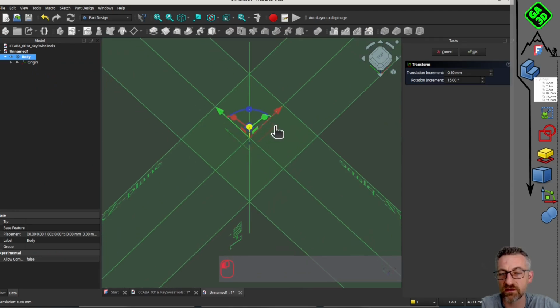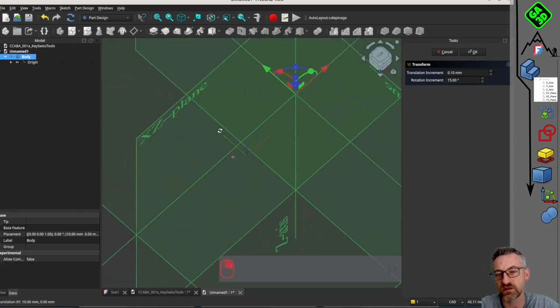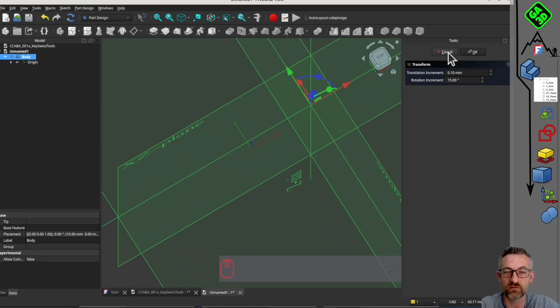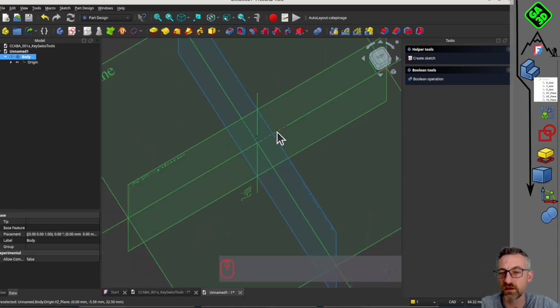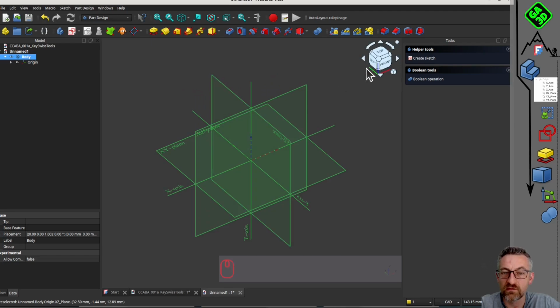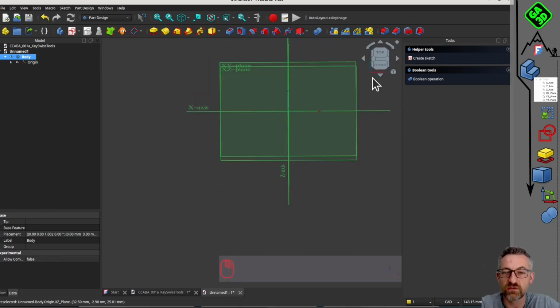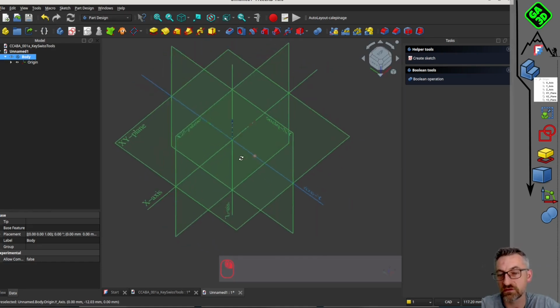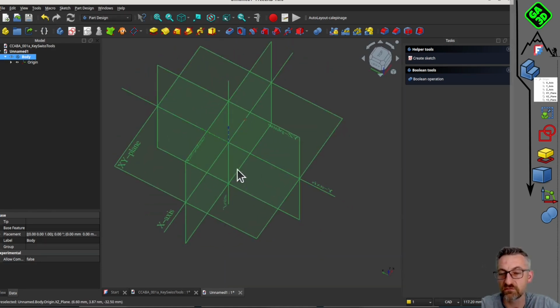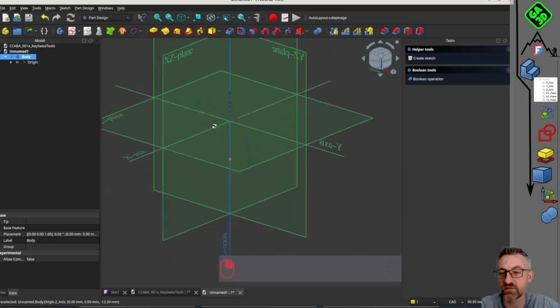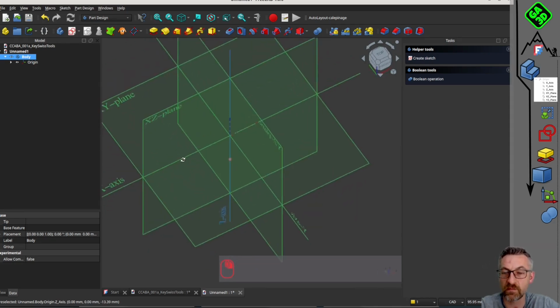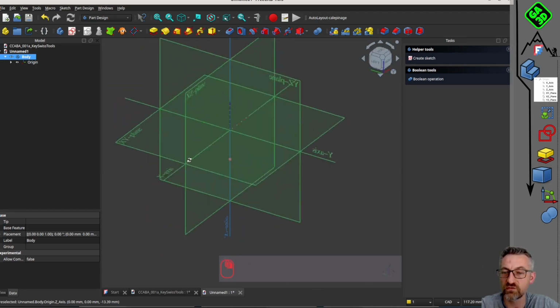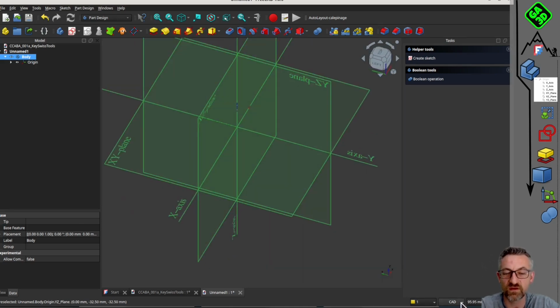There you go. Regarding the interface, I haven't shown you the small logic cube to orient yourself. It's very practical. For rotations, if you see, I press the wheel and the right button, and it allows you to rotate. Change my orientation in the 3D world. So, there are different possible modes. Depending on the software you've already used, you select the one that suits you best. The one I use by default is CAD mode. But if you've used Blender before, you can select Blender, and there you go, you don't lose your habits.